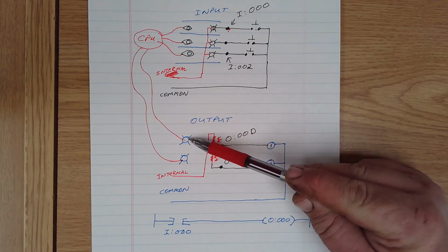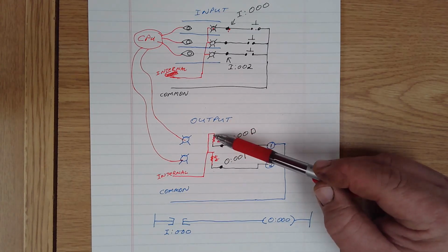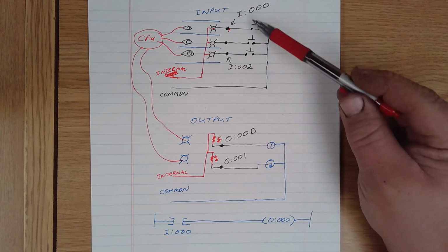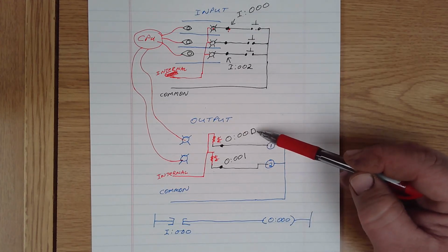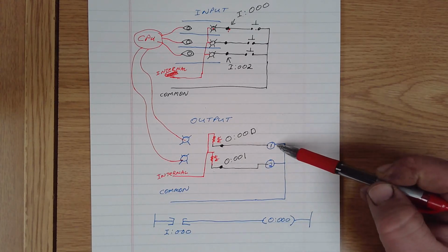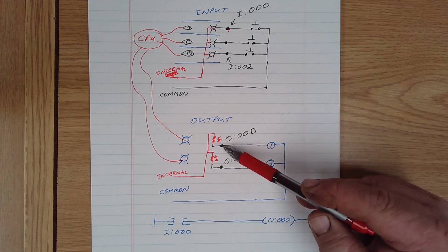So once this lights up, this resistance becomes 0, and current can travel from the output terminal, which is addressed the same way the inputs were. Start with an output and then which number it is. That'll send power out to whichever device is connected to that output.